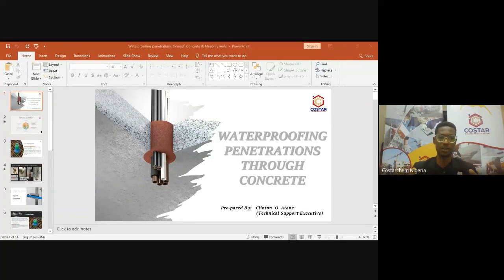According to the technical data sheet of the structural grout, there is a recommended liter of water you have to use per bag of grout when mixing. So, following that strictly, you create your mix using a mechanical speed drill. Now, once this is done, the next thing you have to do is to pour. That's what we call placement.